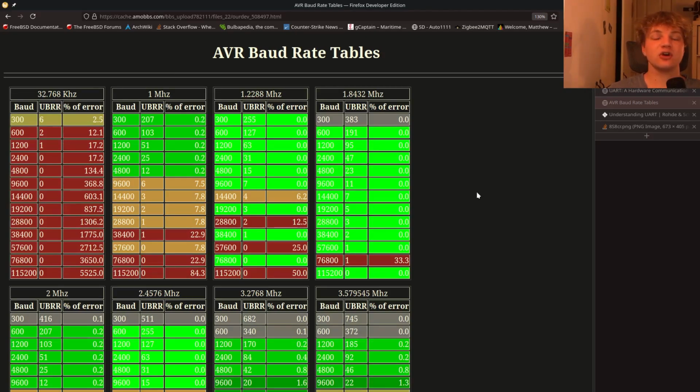Benefits and drawbacks of UART. So with UART, if you've only got 2 MCUs that need to talk, or you need to use it for debug, as I mentioned before, it's great for debug, then you don't need to bother with all of the extra lines associated with SPI or the inherent overhead with I2C. You can just do this. It's flexible in the same way as SPI, in that you can build your own messaging layer on top, and you could even include something like CRC or checksums to detect errors better than a parity bit.